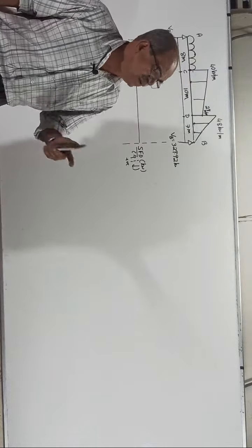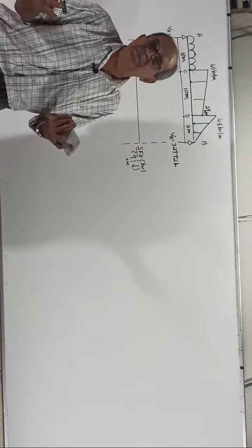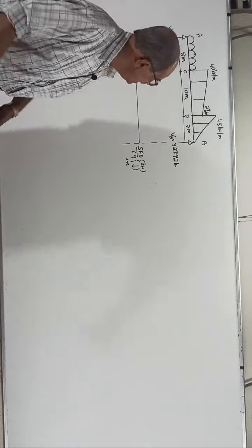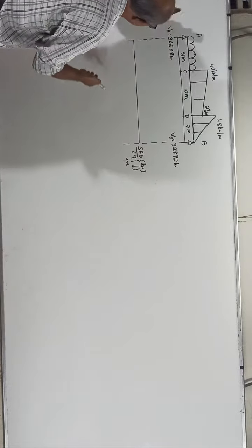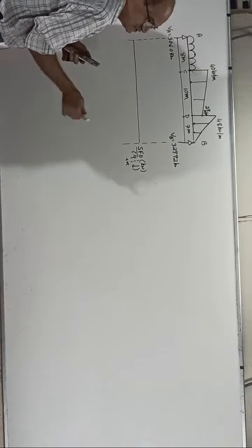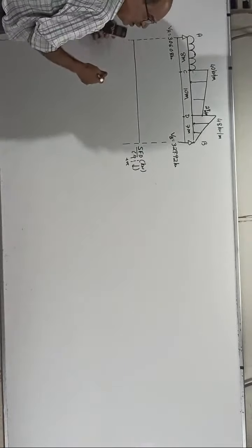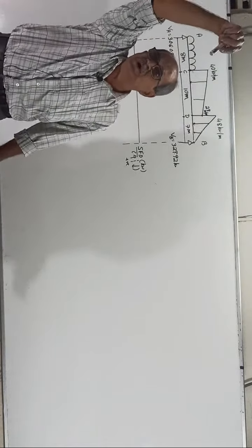And people tell that very authoritatively: BMD jumps, BMD falls. What jumps and falls? First of all, I will tell you BMD will remain there only. BMD will not jump. Okay, start. Now, I told you, start from the left side. You just go with the load. If the load is going up, you go up. If the load is coming down, you come down.